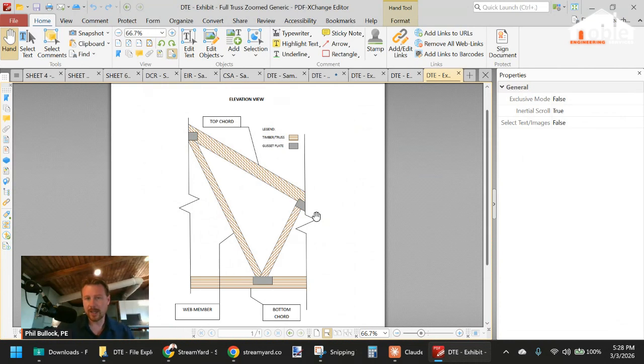I say that because it's not just about trusses, although the word truss is used to define this triangular system of cords and members. It can actually just be general framing. That's why we use the word timber, because a lot of trusses are manufactured, brought on site, installed, and you can't notch them, and you have specific manufacturer's requirements.